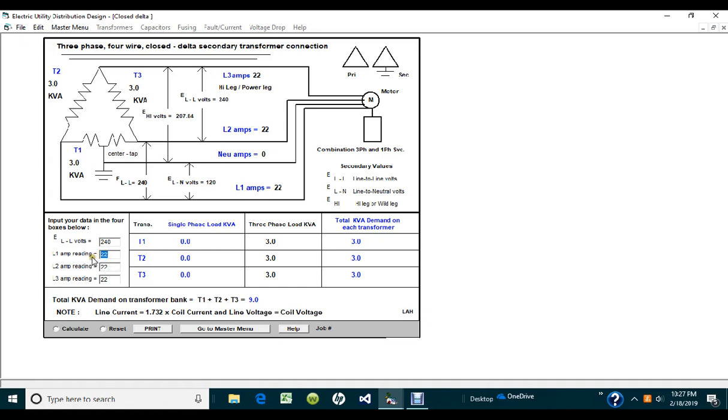instead of having just 22 amps on line 1, he's going to give us another 30 amps of single phase load to be connected to line 1. That's going to be from line 1 to neutral. So he says I have 30 amps of single phase, so that turns out to be added on top of the 22 there. Excuse me. It'll be 52 amps. So 52 amps there, and let's say that it's balanced off.